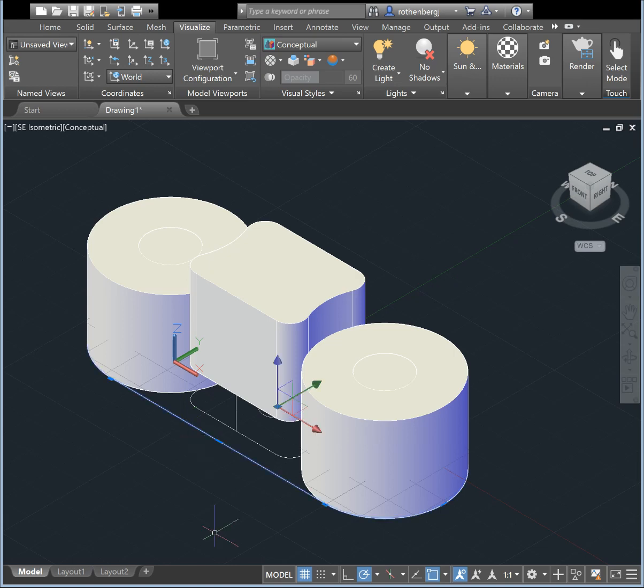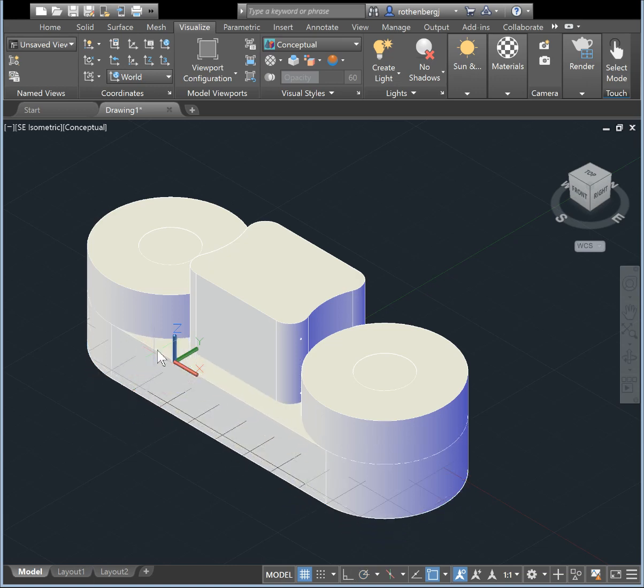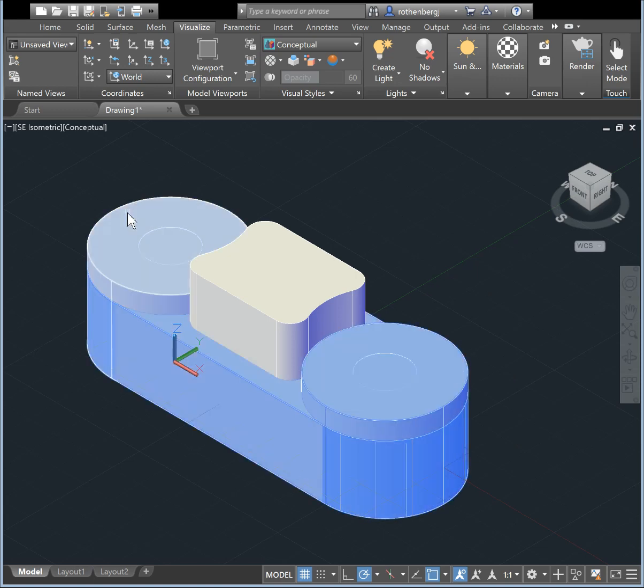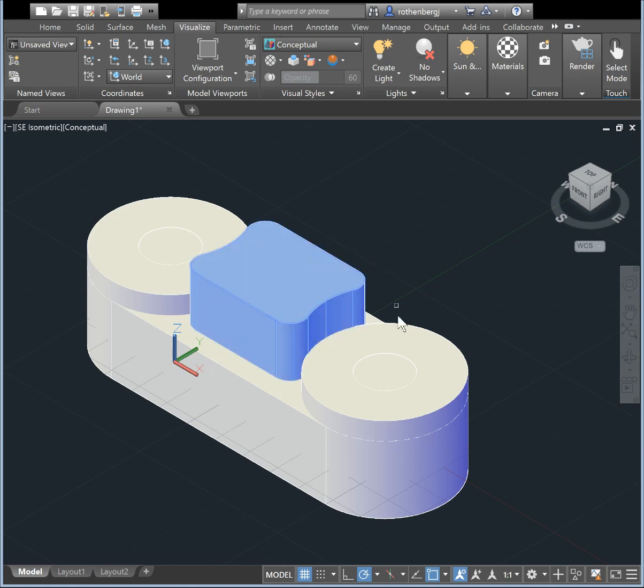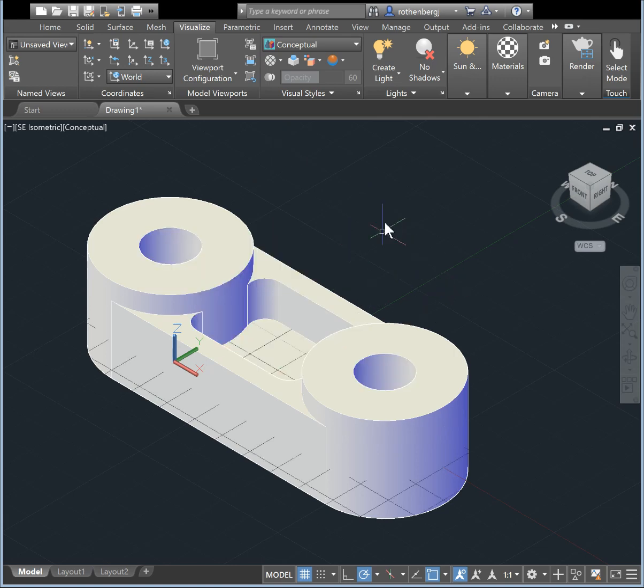And now select the large exterior piece that we made, and we will extrude that up 1 3/16. So now we will use the subtract tool. Enter subtract, hit enter. Now select the main body and the two large circles and hit enter. Now select the piece that we moved up and extruded, the piece in the middle, and the two small circles and hit enter. So this is most of our main shape.